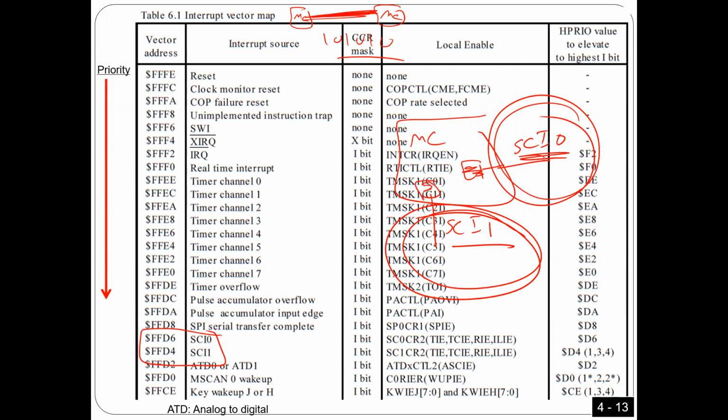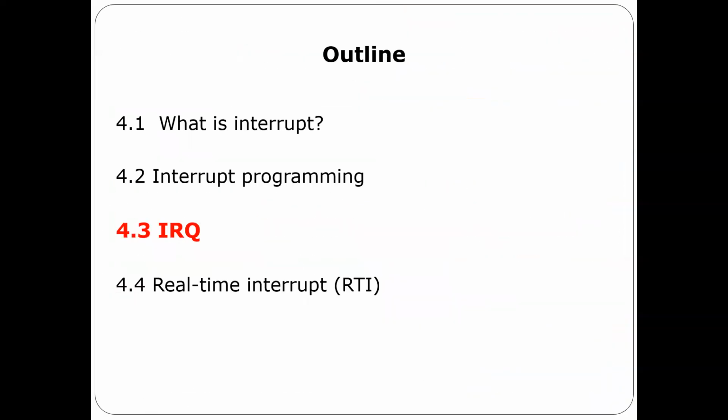Also, you can see we have here a location to put Zigbee. So what is Zigbee? Zigbee is a wireless module. It can also be used to communicate using SCI1. So you can use SCI1 serial communication in order to enable one board to communicate with another board using serial communication. Is that okay? Today I'm going to explain how it works.